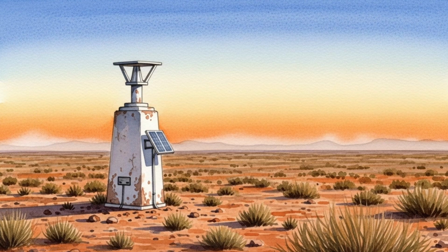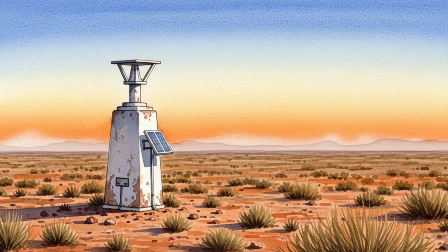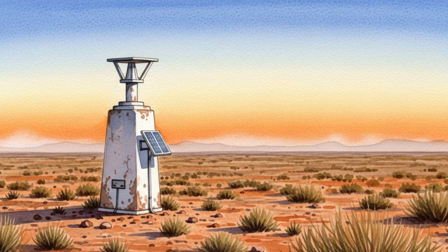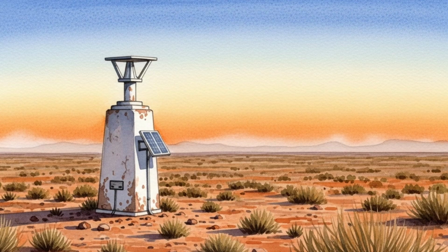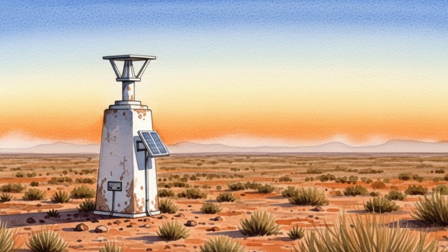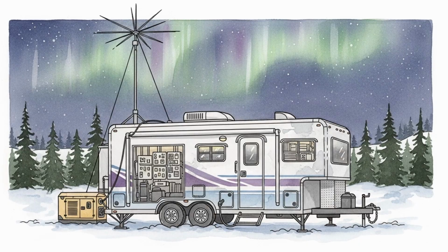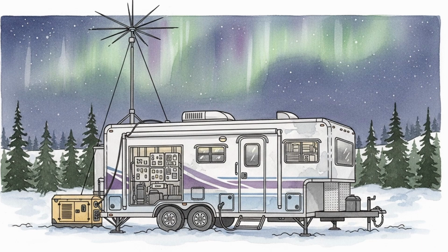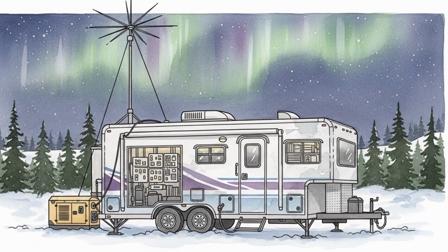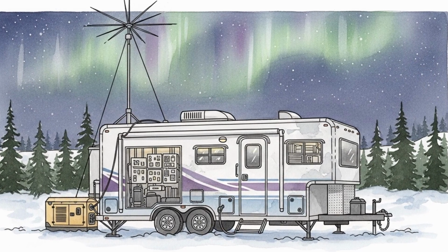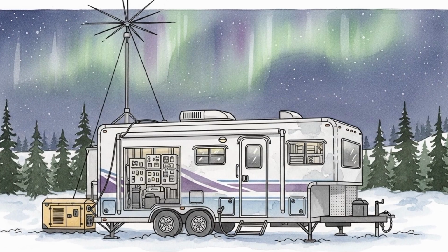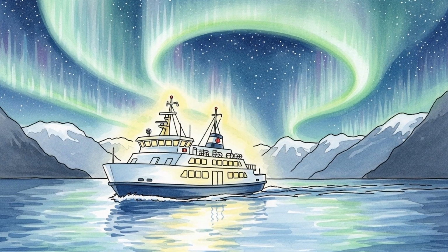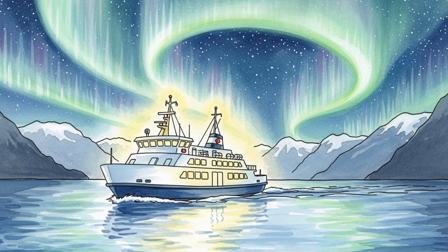In orbit, increased drag lowers altitudes of small satellites with low area-to-mass ratio margins. Catalog errors force temporary expansion of conjunction thresholds. Some operators perform unscheduled orbit determination and small burns. Navigation performance degrades at low latitudes during ionospheric irregularities. Timing networks switch more sites to holdover. Data centers avoid maintenance that would reduce redundancy. Aviation maintains reroutes for the event duration and uses satellite voice and data in place of affected high-frequency paths. Public communication notes limited slowdowns and regional outages. Recovery takes 1 to 3 days after the main phase ends.